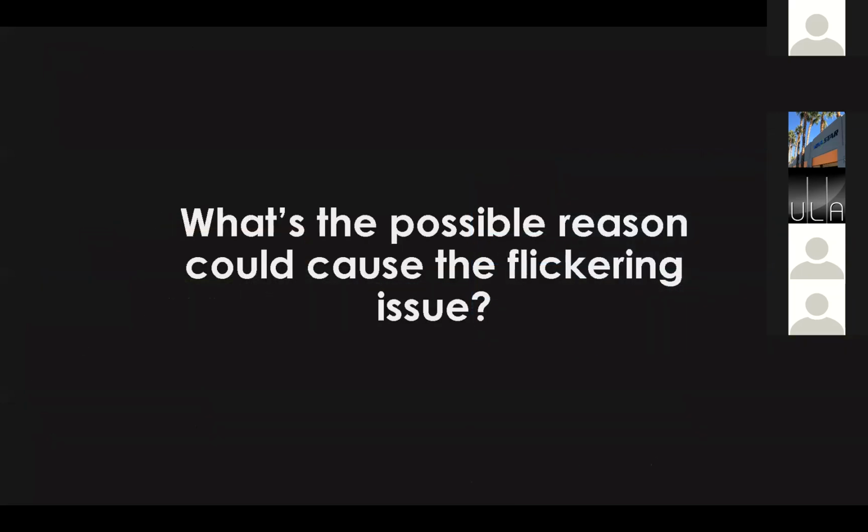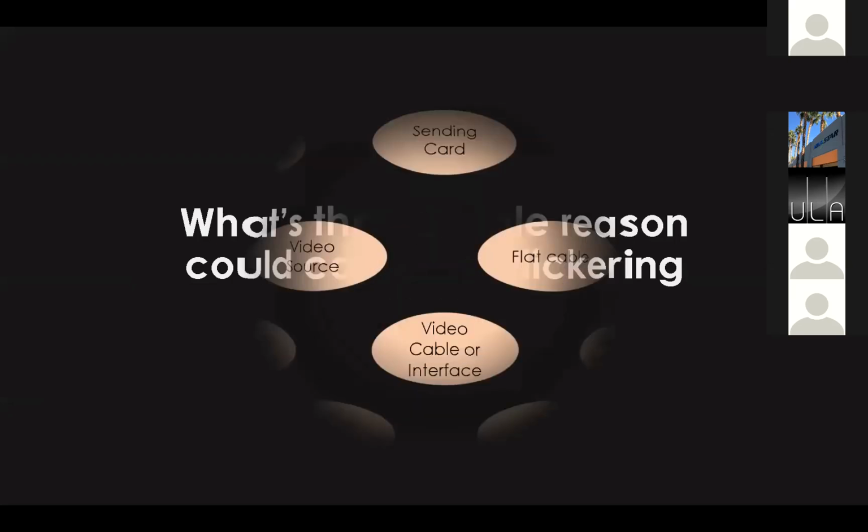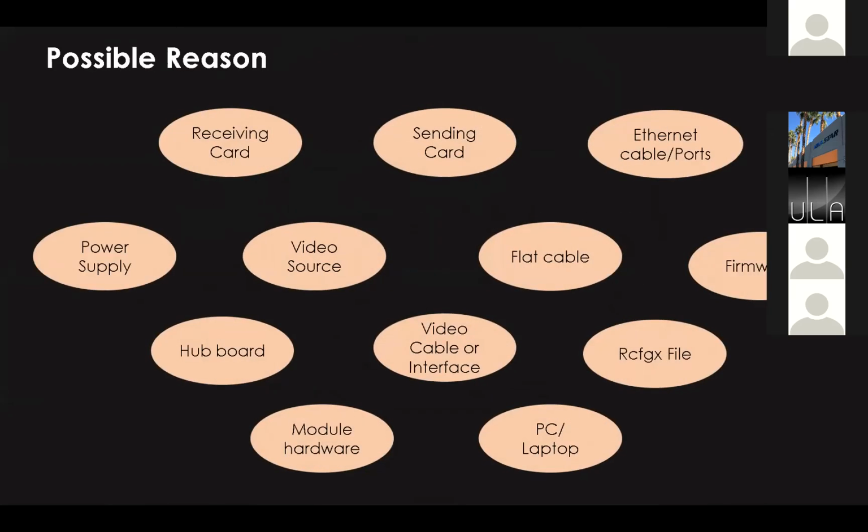So what possible reasons could cause the flickering issue? Let's say these could be the possible reasons: receiving card, sending card, Ethernet cable ports, power supply, video source, flat cable, firmware, hardboard, video cable and the interface, RCFGX file, module hardware, or the PC or laptop issue.